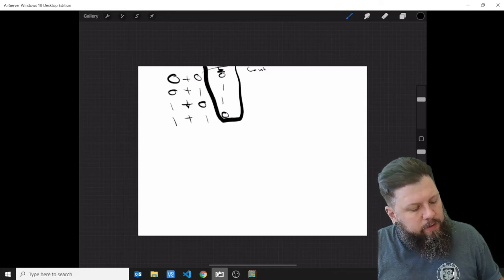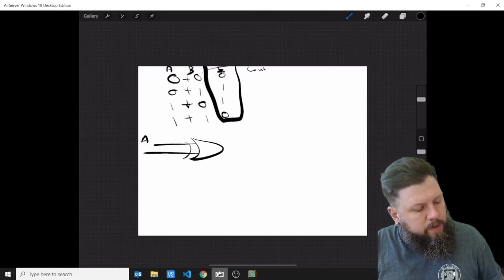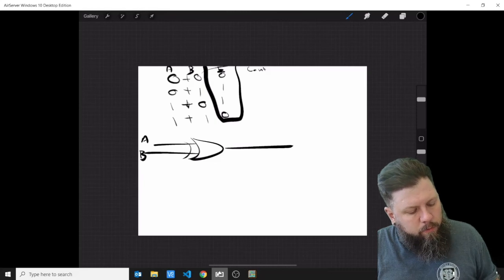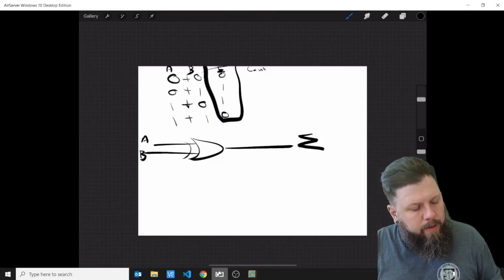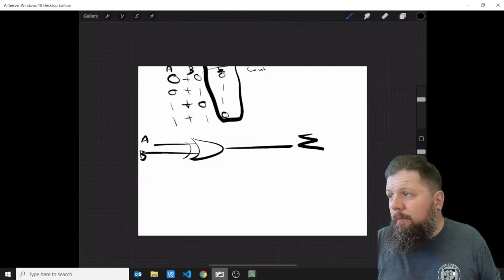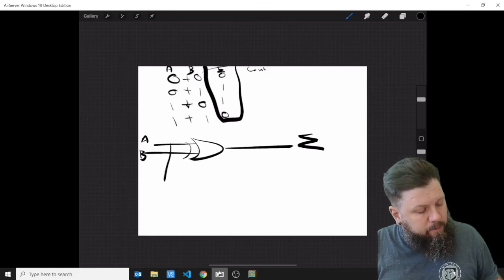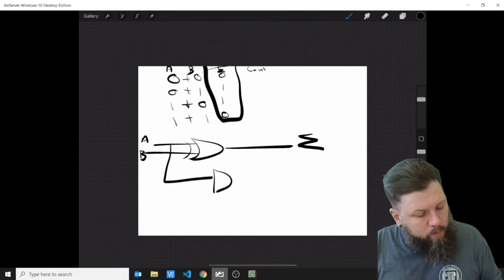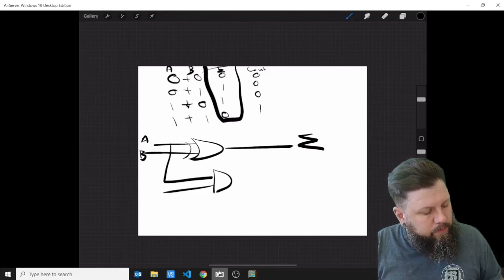Okay? Cool? What is this right here? That's an exclusive OR, right? Now we know how to make an exclusive OR, so let's say we've got A and B right here. Boom. We've got our sum, and then this carry out bit, we'll take the A and B, and what is it? It's 0, 0, 0, 1. It's an AND gate, right?